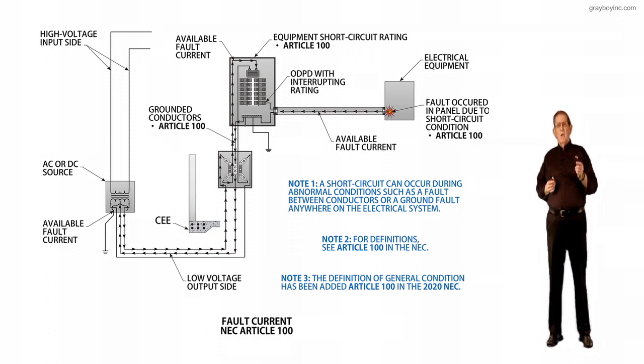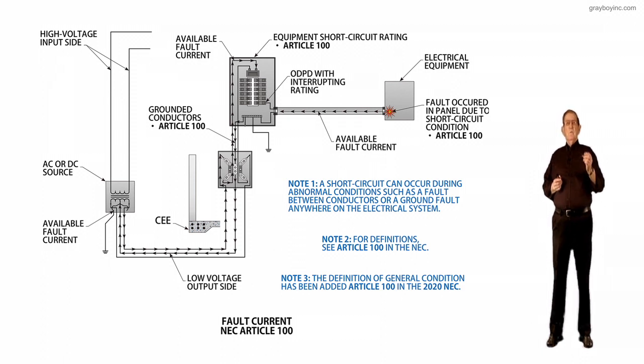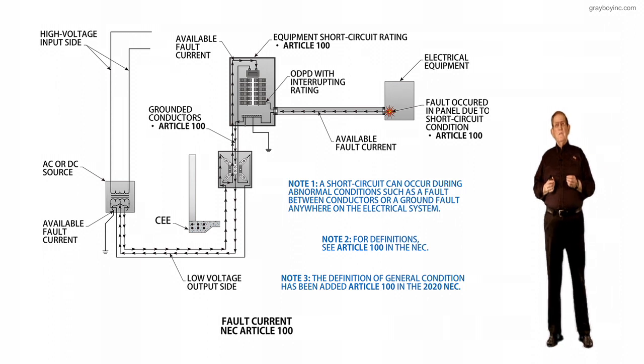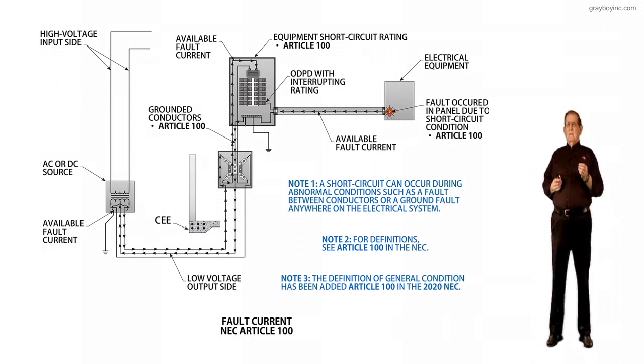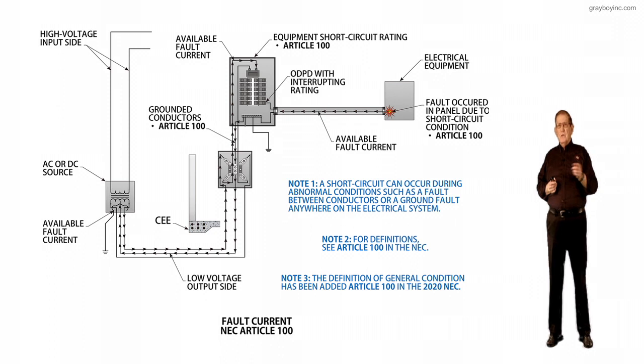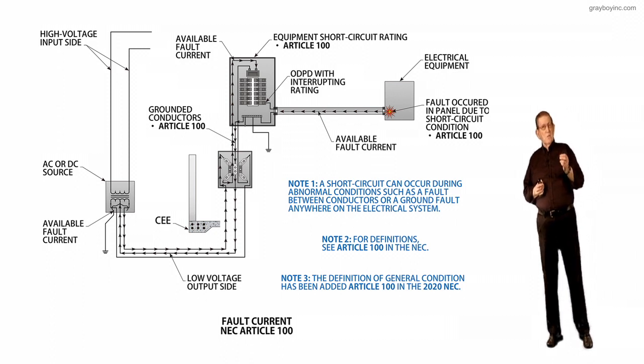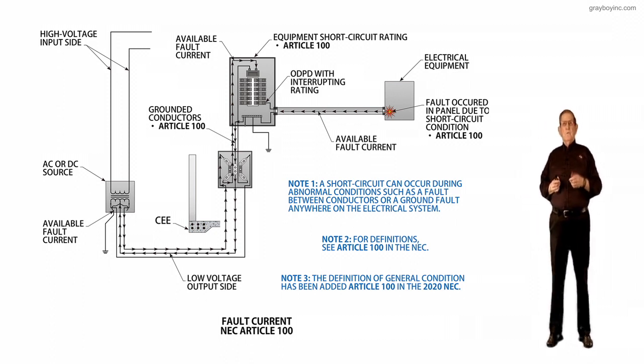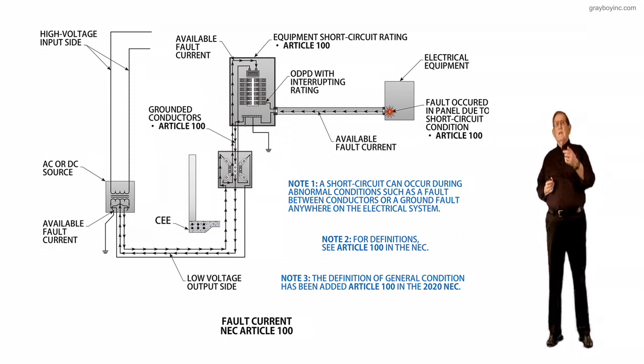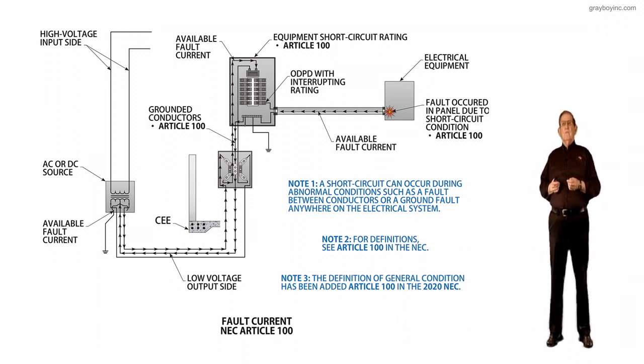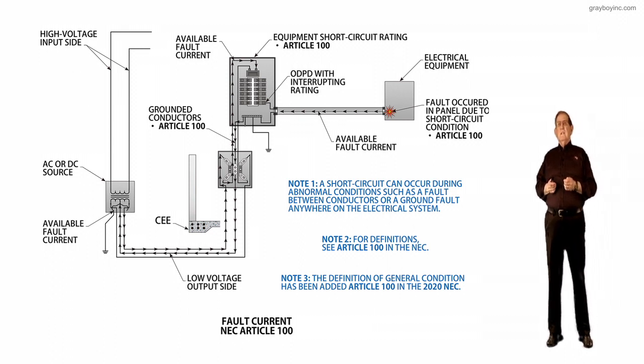Now, first of all, to really get a real handle on this, you would review 250.4(A)(5), and it explains that to clear a fault, you had to have a low impedance path, and the earth could not be used as a sole means to clear a fault. So if you ground the transformer, you have to ground at your first disconnecting means. Sometimes utilities will even have you ground at the meter too. But that's based upon a utility requirement, not the NEC.